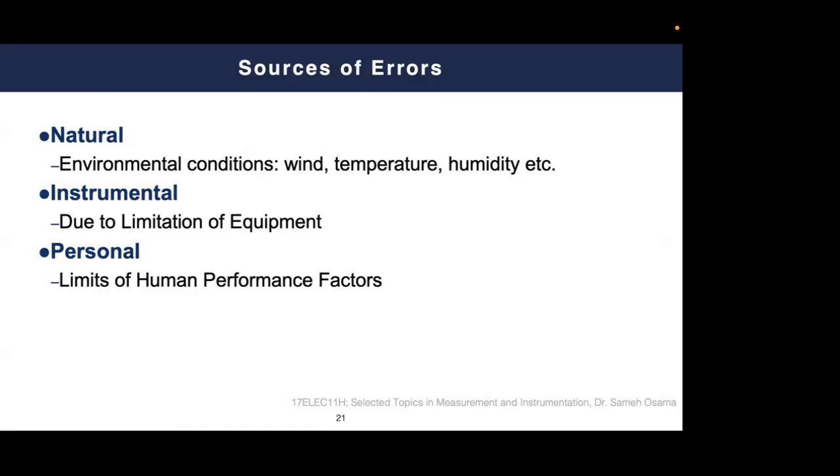Additionally, you might have an error due to the instrument itself, which we call the instrumentational error. If you return to the previous part of the first lecture, where I considered the word calibration, it is very important here. You can control, or at least recognize, your instrumentational error by using the calibration process.